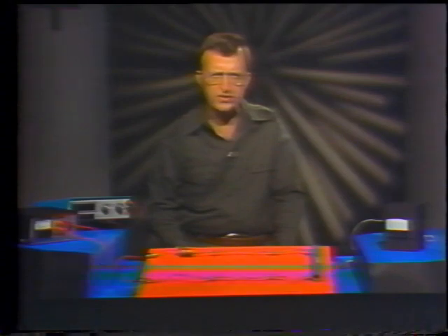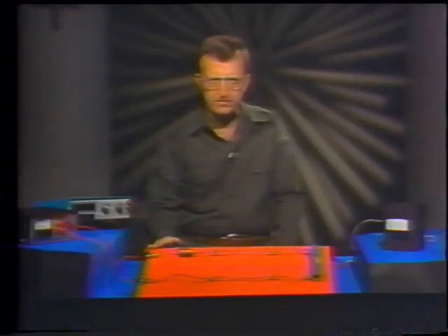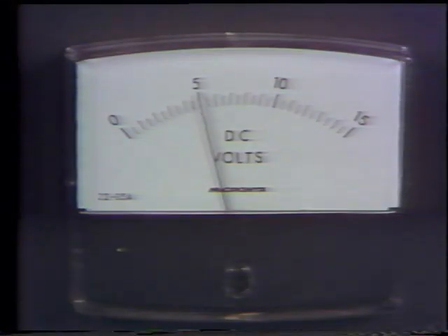The resistor in this circuit has a resistance of 10 ohms. In a circuit like this with only one resistor, the amount of voltage across the resistor is always equal to the source voltage. Now, in this circuit with the regulated power supply, the source voltage is known. It's 5 volts. We'll have to measure the voltage across the resistor. And when we hook up the voltmeter, we see that the reading is 5 volts.